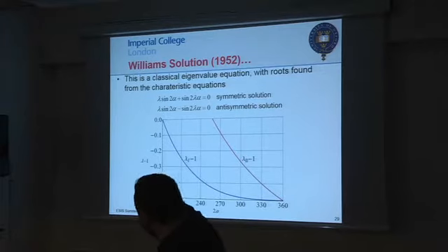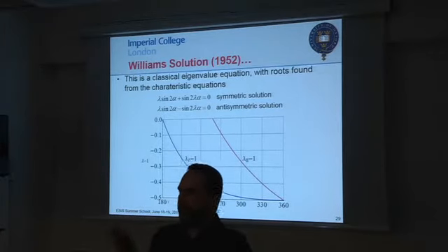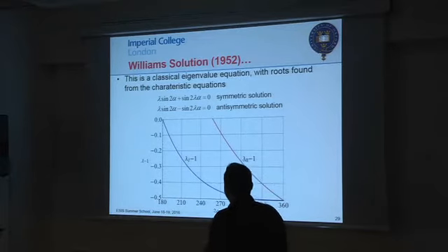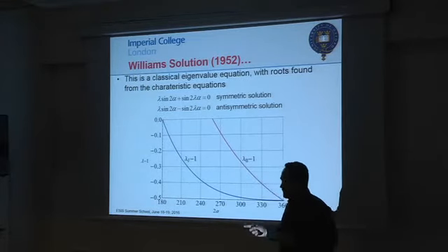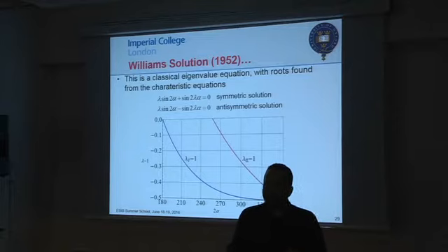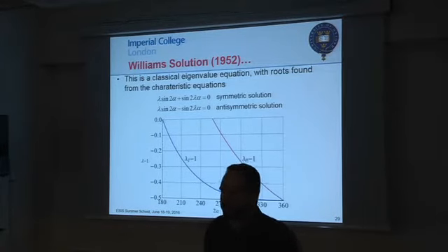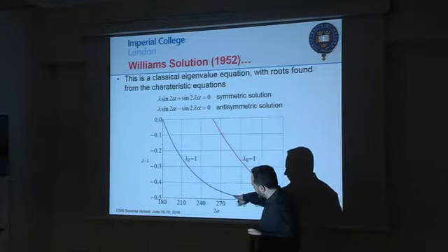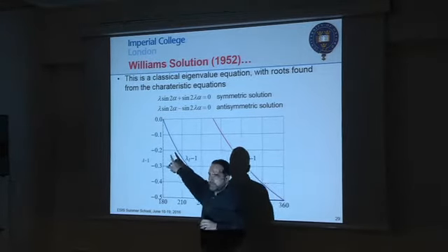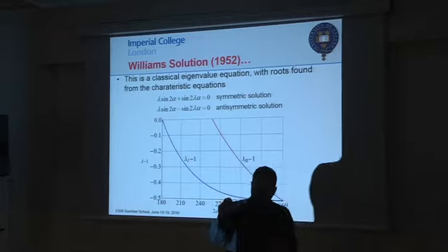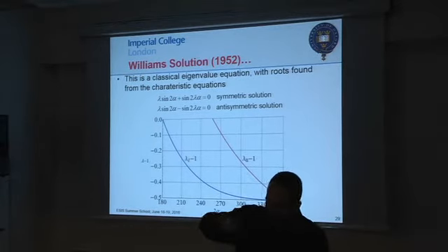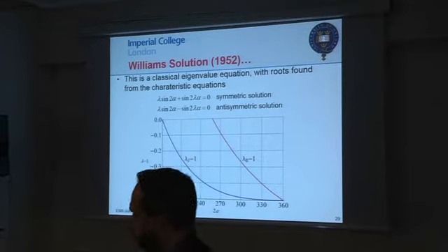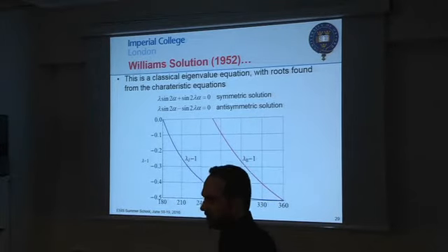Now, obviously, the only time when it's not singular is when that notch becomes so big that you have a flat sample. So in mode 1, no matter what you're doing, even if your singularity becomes weaker and weaker, so if you go from a crack to a larger notch, it's still singular: the stress field in the corner, due to the application of a symmetric load, is singular. There's nothing you can do about it.